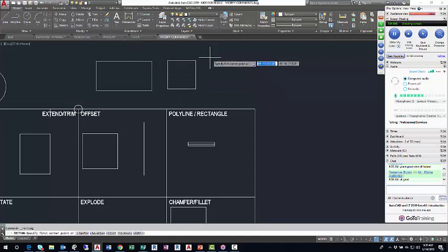The first corner is created, and then you move diagonally away. It doesn't have to be down, it could be up, whatever, but just diagonally. If you just go to the right, it'll create a very thin rectangle. And at this zoom factor, I can't tell it's a rectangle. Rectangle, left click, left click.